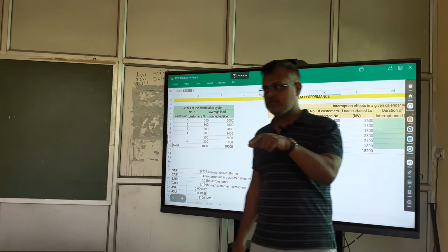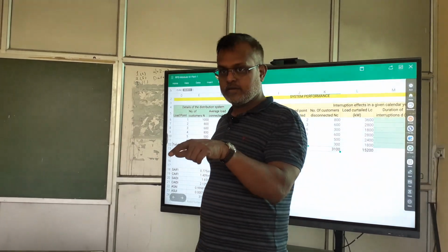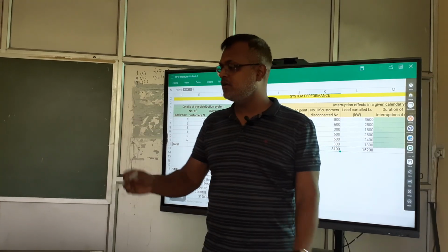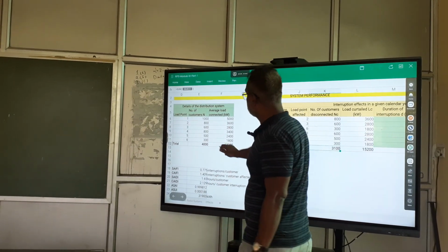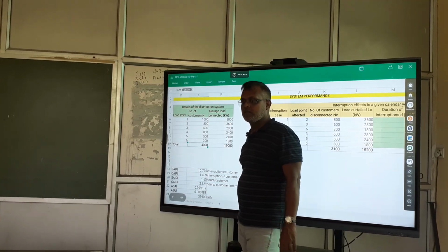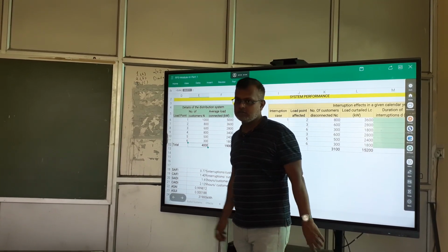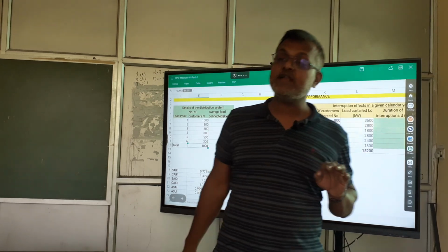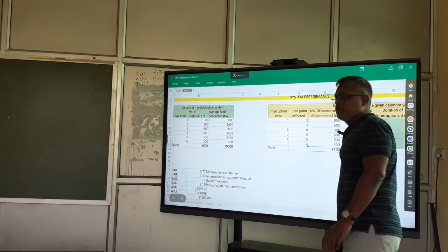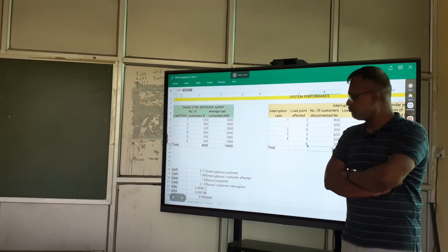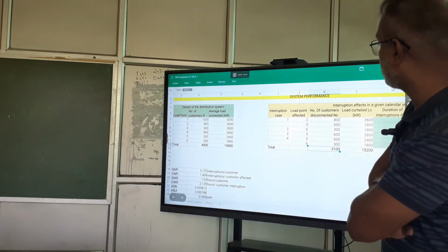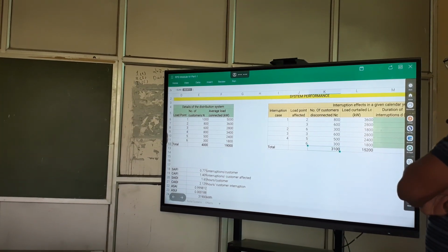So this is Ni, right? Number of customers affected N. You can mention that. Total number of customers N is equal to 4,000. Number of customers affected by interruption is equal to 310.